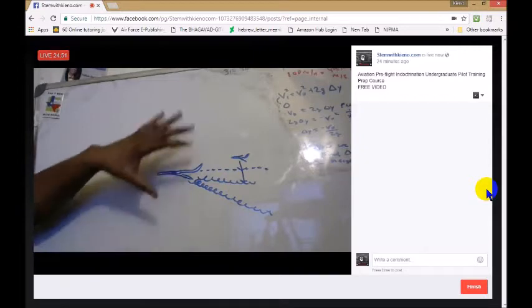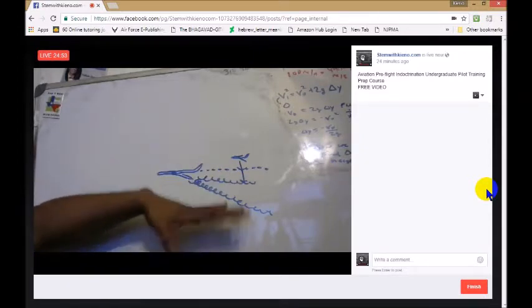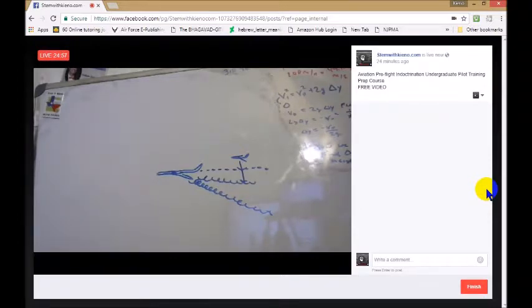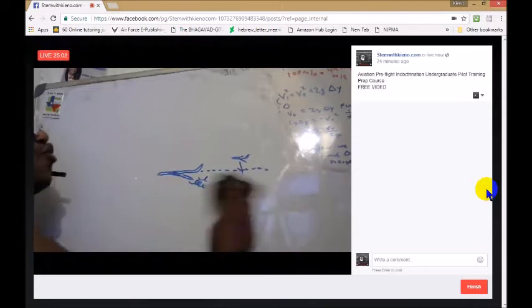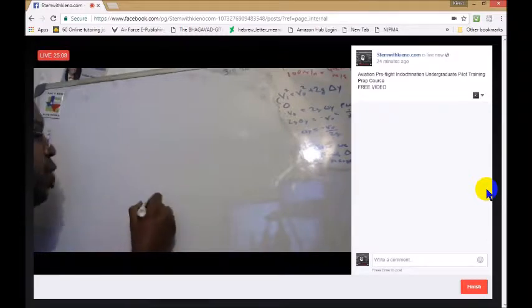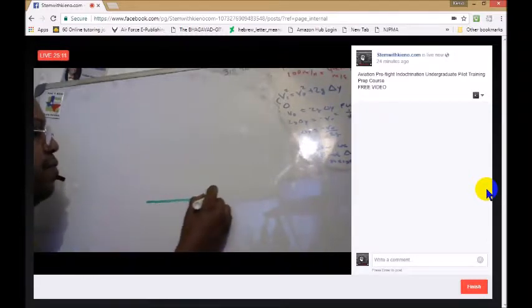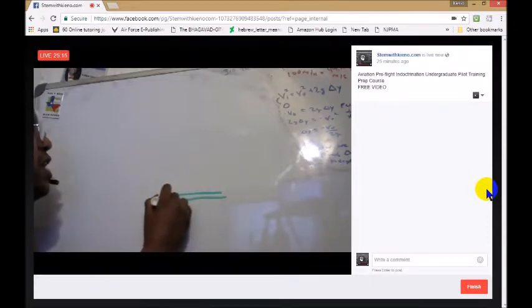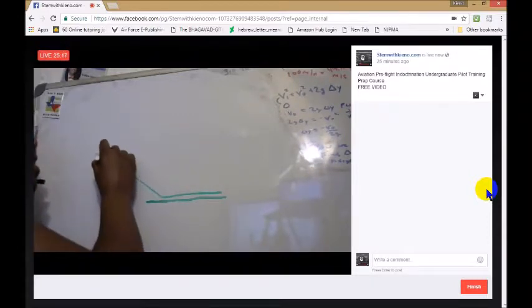All right. So induced drag produces wingtip vortices, and we need to stay at or above the flight level of the aircraft producing those wingtip vortices. They're very strong when the airplane is on climb out. So just to give us an idea, let's say we have a runway right here, right? This is the runway. And our larger aircraft kind of takes off like that.